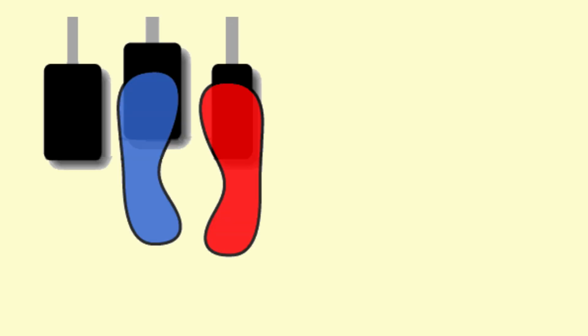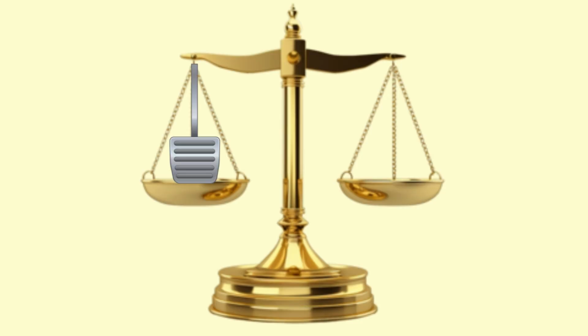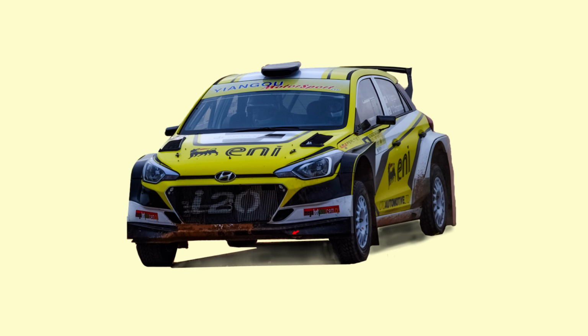Another method to reduce understeer but safely avoid oversteer is left foot braking, whereas the weight now shifts forward and the increased load on the front tyres will allow them to utilise more grip and now improve that initial turn-in which was so understeer prone in the first place. Left foot braking also provides a more neutral driving style at the limit with its balance between braking and acceleration. We see this technique often used in rallying to manage traction and control the car on loose surfaces.